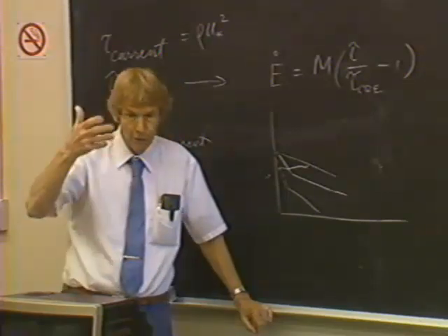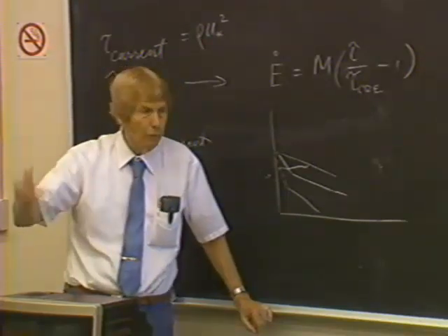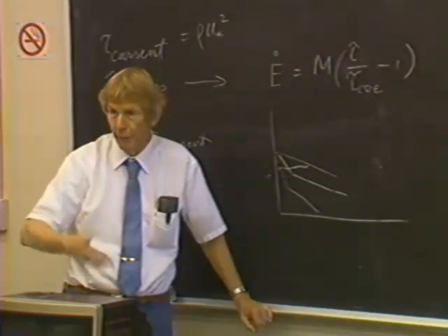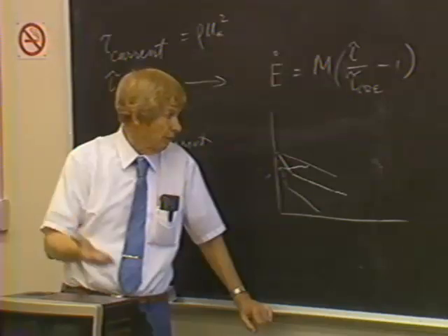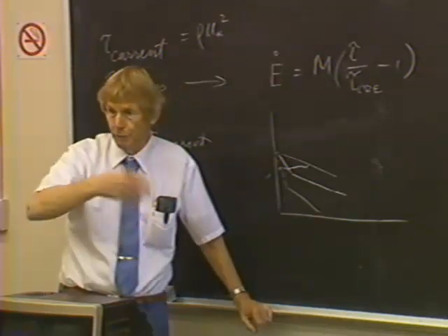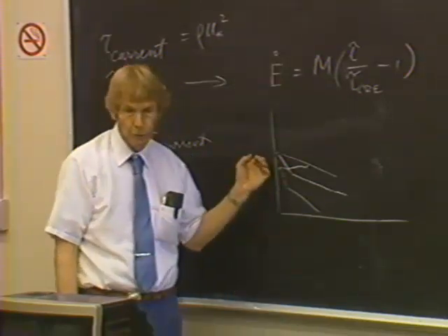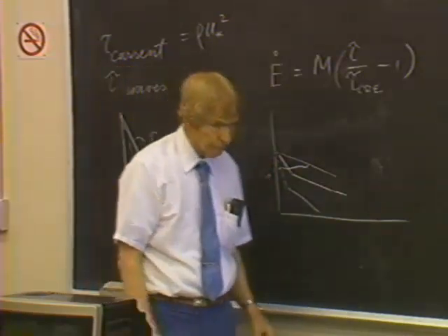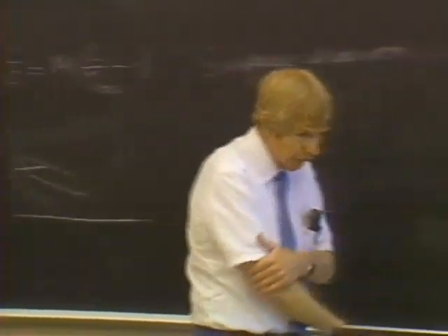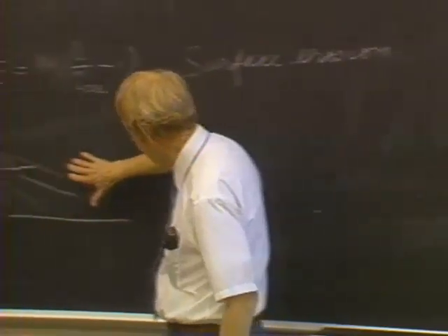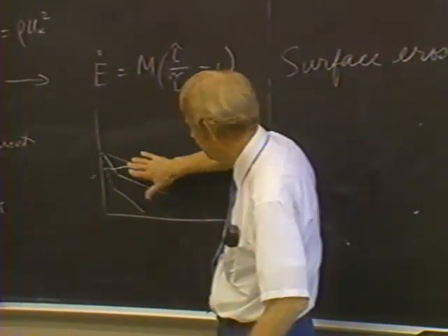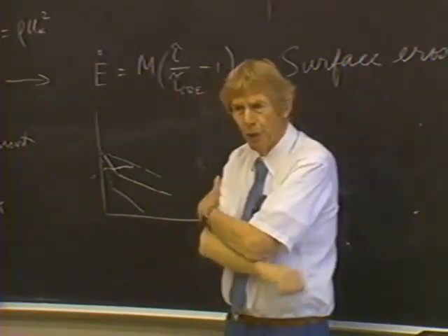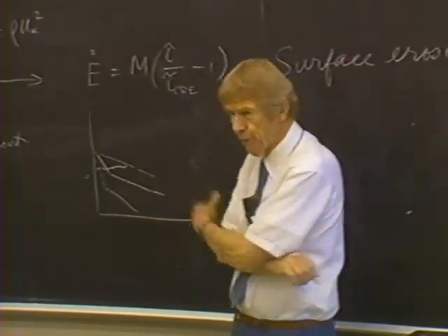But typically the material comes and is deposited in shallow bays, and then during the year it's suspended day after day after day, so it never has a chance to really consolidate or gel, and it's easily resuspended and transported onward. I'll show you that Monday. If the material forms a gel, becomes sort of a uniform gelatinous material, then a different process takes place from what we described here, surface erosion.